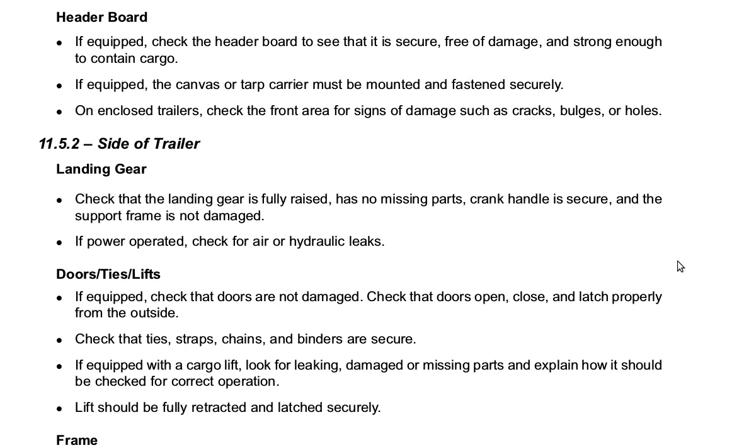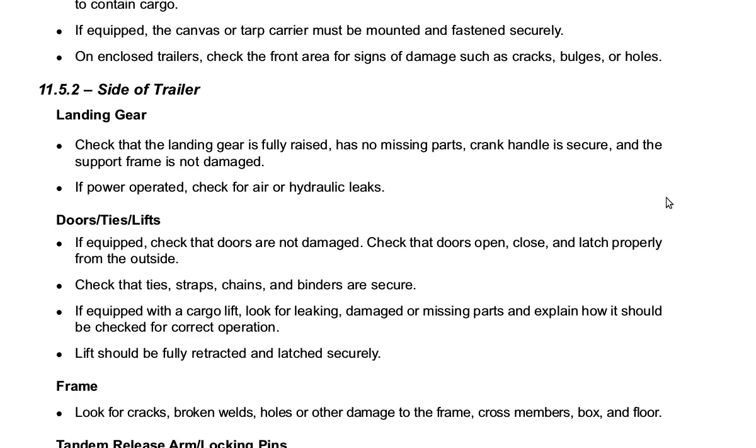Side of trailer. Landing gear. Check that the landing gear is fully raised, has no missing parts, crank handle is secure, and the support frame is not damaged. If power operated, check for air or hydraulic leaks.